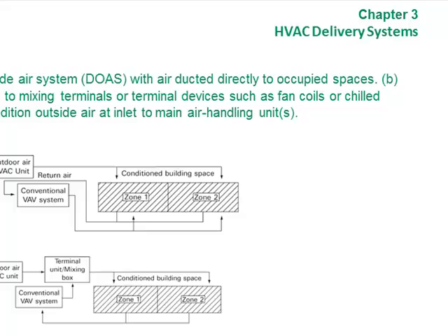And so you can turn it on when it's 80 and turn it off when it's 70. You can turn it off at night. Yeah, turn it on during the day. Yes, keep it off at night. Small offices, medical buildings, stuff that have open doors continuously.